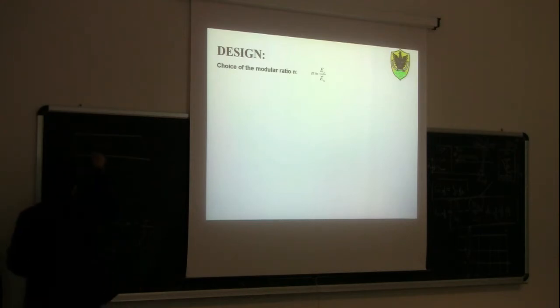So on this side, we will have an opening of the joint, so we will have something like this because of the bending moment. Here we have contact, so here we will have a distribution of stresses, something like this. Then here we have a rebar in tension, and here we have another rebar in compression.